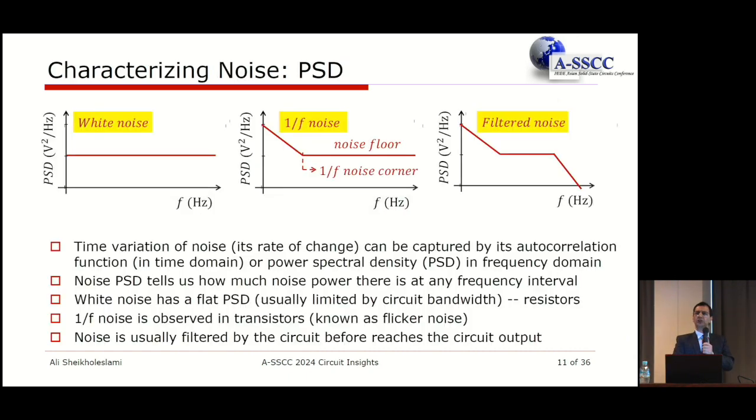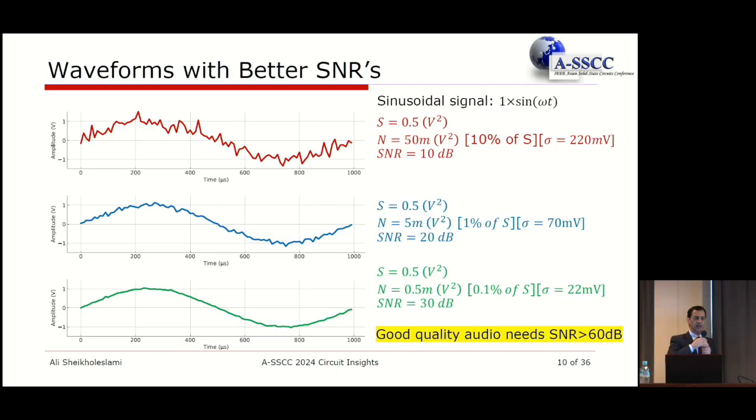So far, what we talked about here was looking at the signal power and noise power, that seemed to be just one number. And that is not enough for us. What we need to know is how that power is distributed over frequency. In other words, we need to also know how fast is that noise moving.